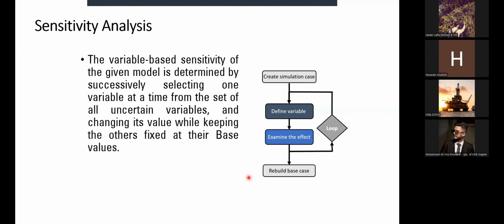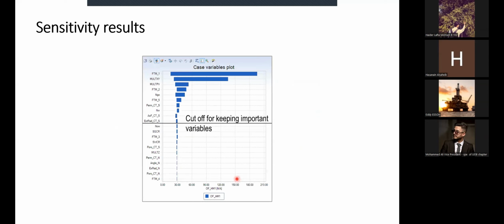So this is the idea of sensitivity. What the simulation will do, you will list here, as you can see, tens of uncertain parameters. That means, let's read it. The fault transmissibility, the transmissibility multiplier, the pore volume, I don't know what this is, net gross or what. For example, critical gas saturation, aquifer extended radius, many inputs that you suspect, you are not sure. What you tell the model is, check each one at a time and tell me the impact.